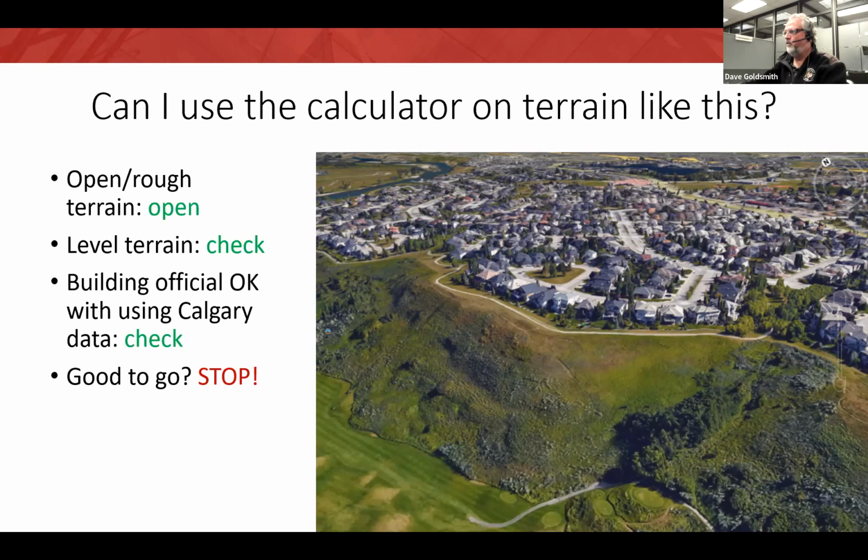So this whole row of homeowners hired a consultant to investigate whether or not these windows were code compliant, probably as a precursor to seeking compensation for the window replacements from the window fabricators. However, these were permitted under the old A440 system, where to be code compliant, you needed to be A3, B3, C3 and no more in housing and small buildings. It did not mention anything about wind speed up over hills or escarpments. So they were code compliant, but not sufficient for the wind loads they were actually going to experience.